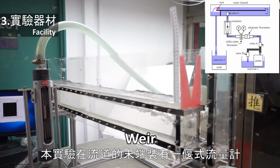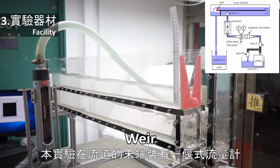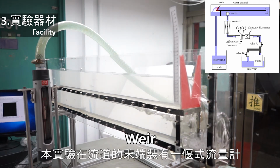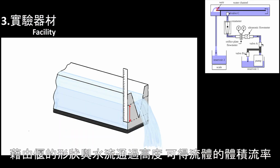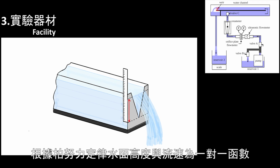Now we come to the measurement in an open channel flow, which is achieved by a weir installed downstream of the top channel that is open to the air. With a given weir shape and the height of water level, we can acquire the volume flow rate. This is because the elevation of flow height is a consequence of the pressure. The pressure is built up due to the weir blockage, and it is a one-to-one function of the flow velocity. The relation can be approximated by the Bernoulli equation.